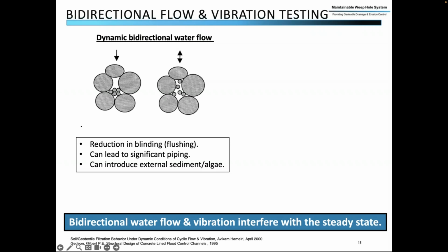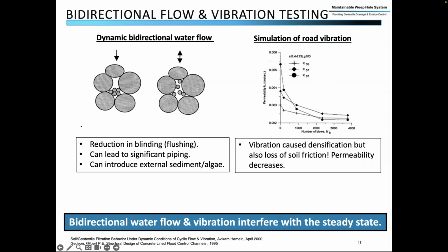So if you have a drainage outlet that is along a riverbank or anywhere that is going to have higher water levels, you've got water going into the drainage outlet, those will disrupt the backfill and cause a decrease in the performance faster than if it was just a land-based application.